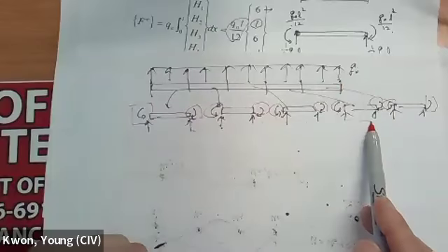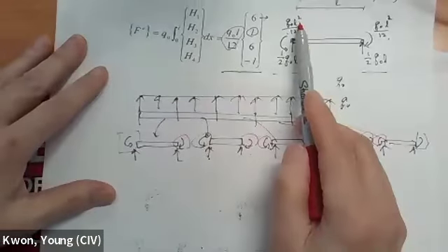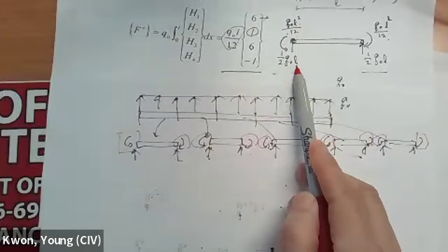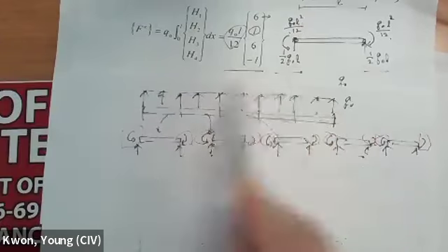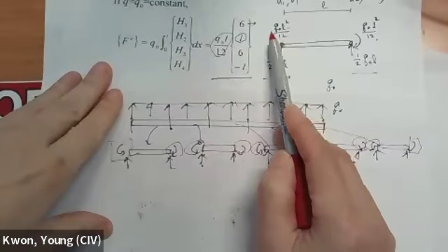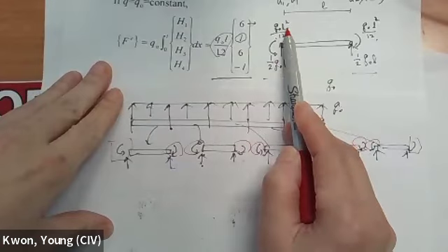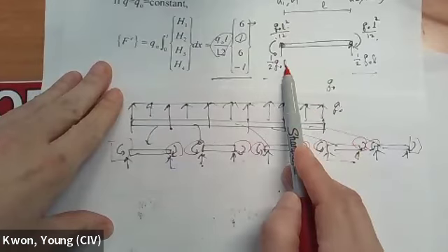Only forces, right? But also, if you see, this is L squared, this is L. So if you refine the mesh, the element size becomes smaller and smaller. What do you see? This is going to be much smaller than that, because this is second order and this is first order.